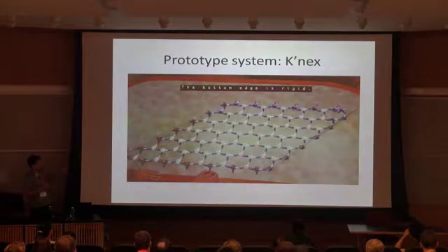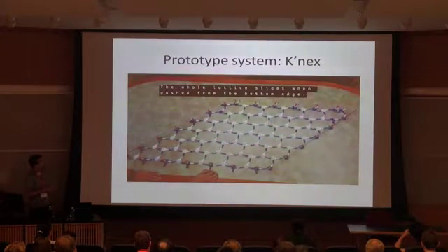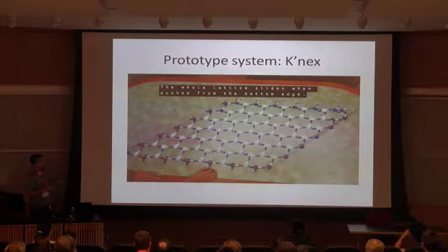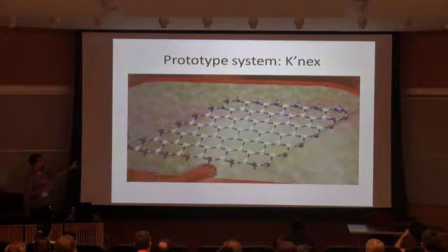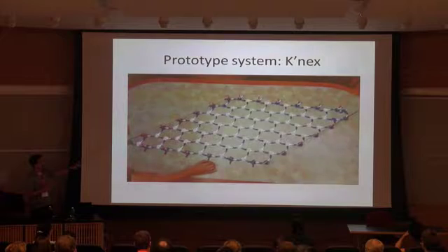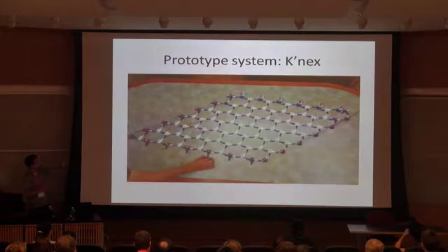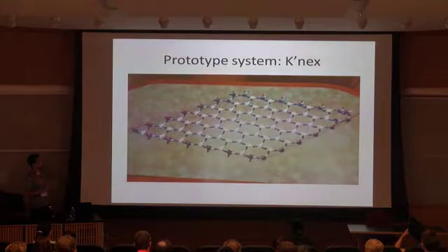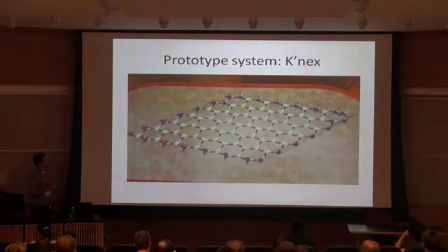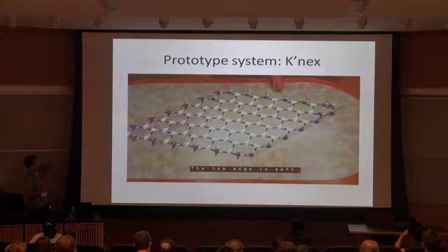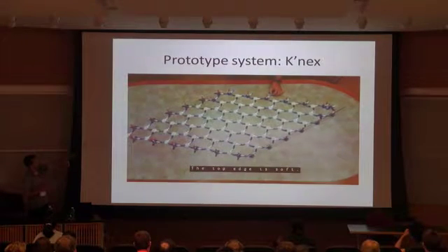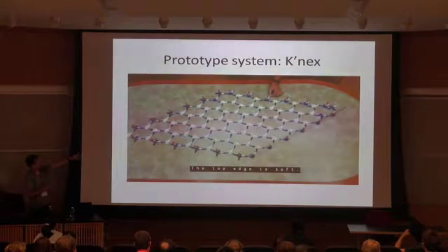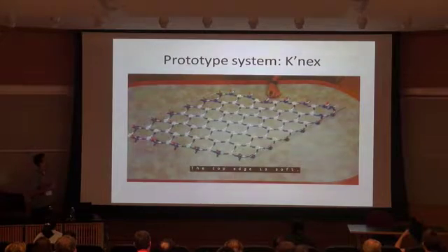I'm going to push on it just like I did before. And you can see it's actually sliding across the table now. Before it crumpled. Now I haven't added any extra bonds to make it stronger. All I've done is change the angle between bonds, but it's gotten much stiffer. Now it won't crumple. Now it's strong enough to slide across the table. I go over to the other side. This is the side that should have twice as many zero modes. It's still floppy. In fact, it's even floppier because it has more zero modes, so it has more ways it can deform.